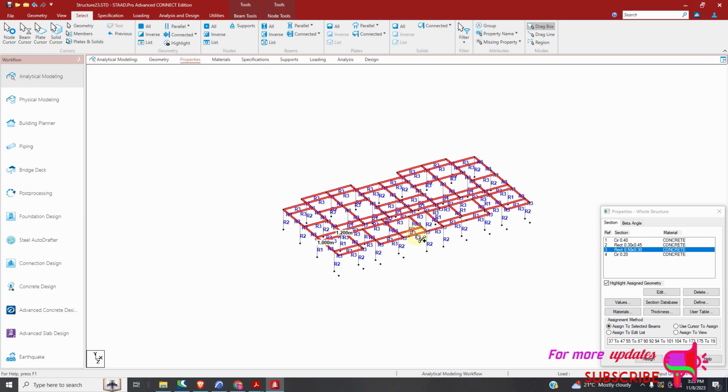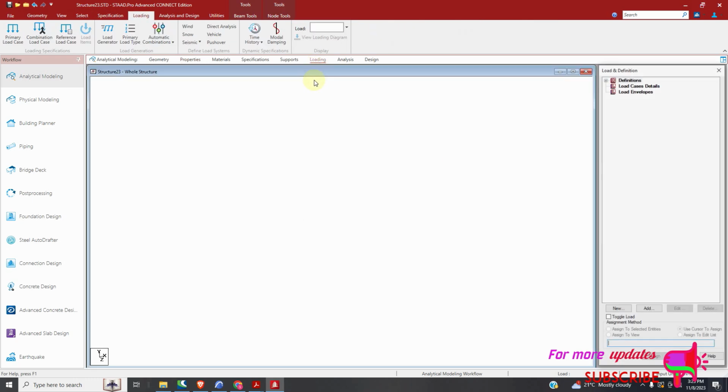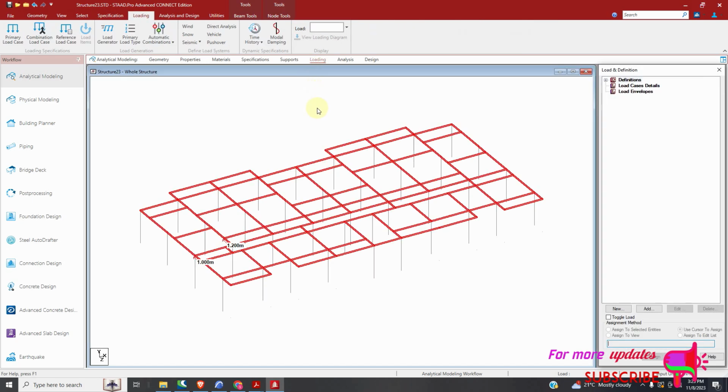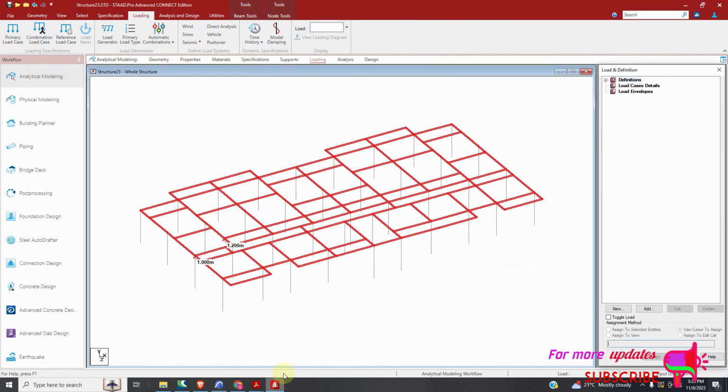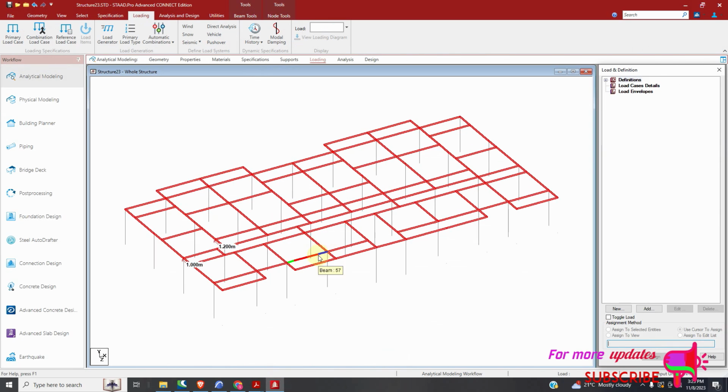So there are two ways you can model slabs. You can either model them as load, by adding a floor load, or you can just model them, right? But I've got to be careful, because if you model using floor load, you have to add a master slave node for each floor, because a slab is not like a void. The slab is connecting all the nodes.